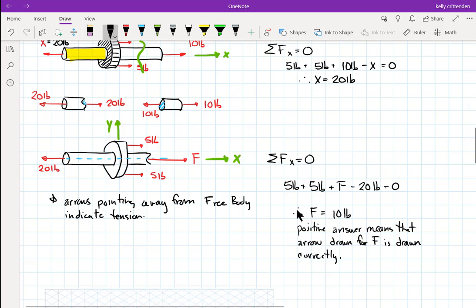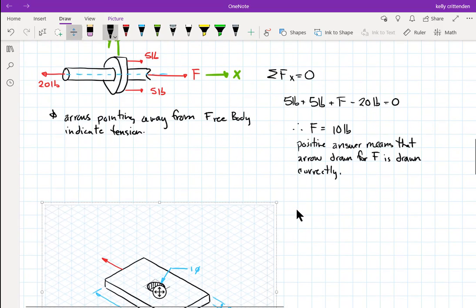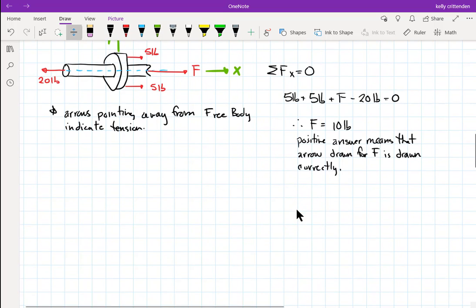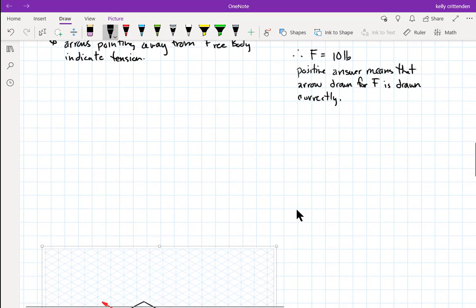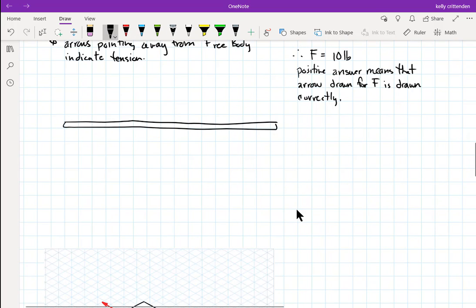Another reason you might need to know is this. So let's say you have a bar of some kind, but it's really thin. Like this. And you put it in, this would be tension. So sigma equals F over A, that's fine. But the same bar, and you put it in compression, even if it's metal. So now, even if this was a metal bar, but it's really that size, really long compared to how wide it is, and then the equation, sigma equals F over A, is still true as far as compressive stress goes, but the failure mode is way more likely to be buckling.